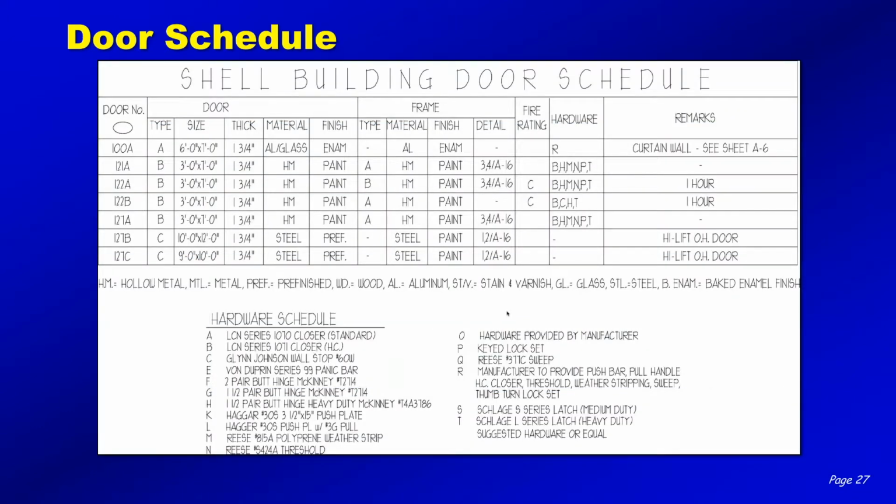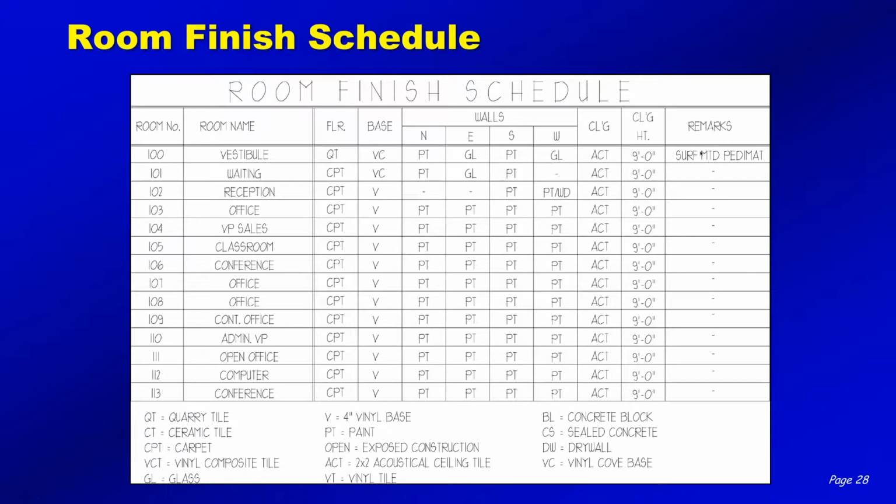So that simple door schedule, where they identify every room in the facility, tells you what the door type is, the size of the door, the thickness, materials, finish, and over here off to one side, any particular notes. Same thing with a room finish schedule. And notice this is why you need to know plan north. They only tell you what it's paint or glazing as you walk through there on the north, east, south, and the west walls.